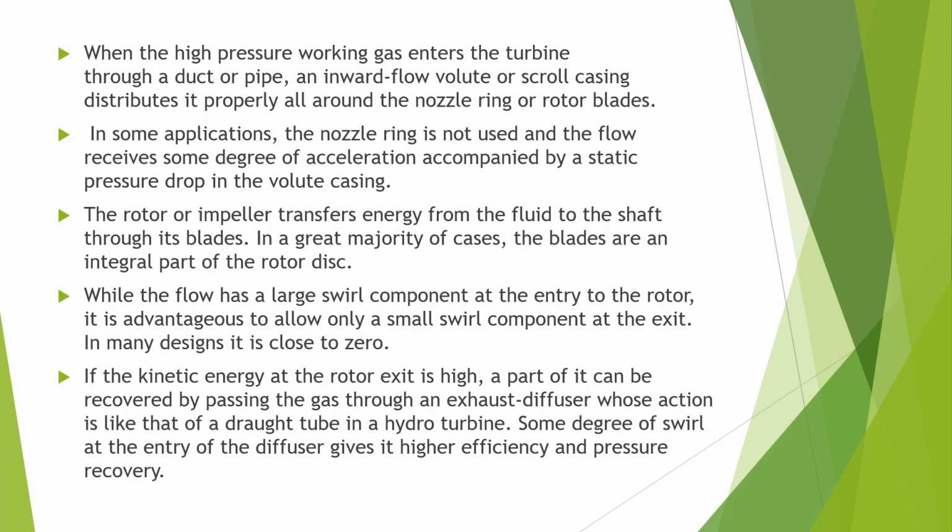The rotor or impeller transfers energy from the fluid to the shaft through its blades. In a great majority of cases, the blades are an integral part of the rotor disc. While the flow has a large swirl component at the entry of the rotor, it is advantageous to allow only a small swirl component at the exit. In many designs, it is close to zero.